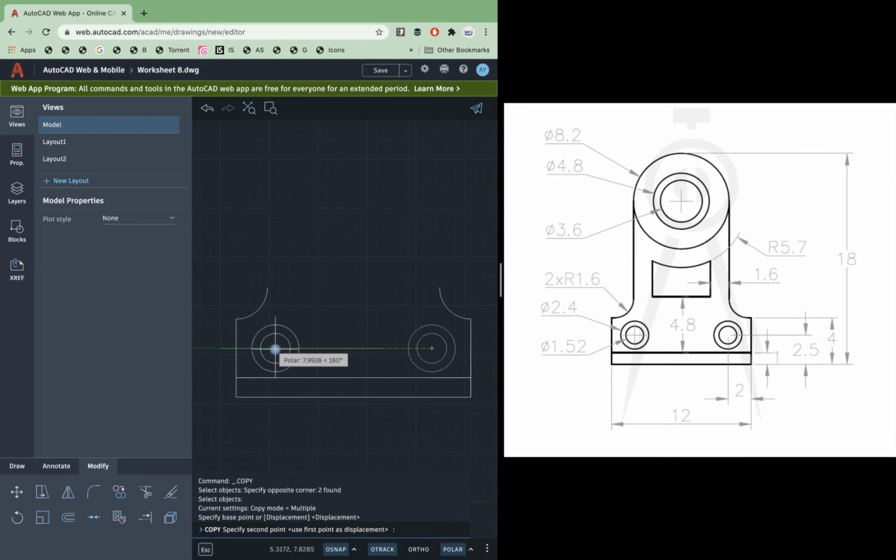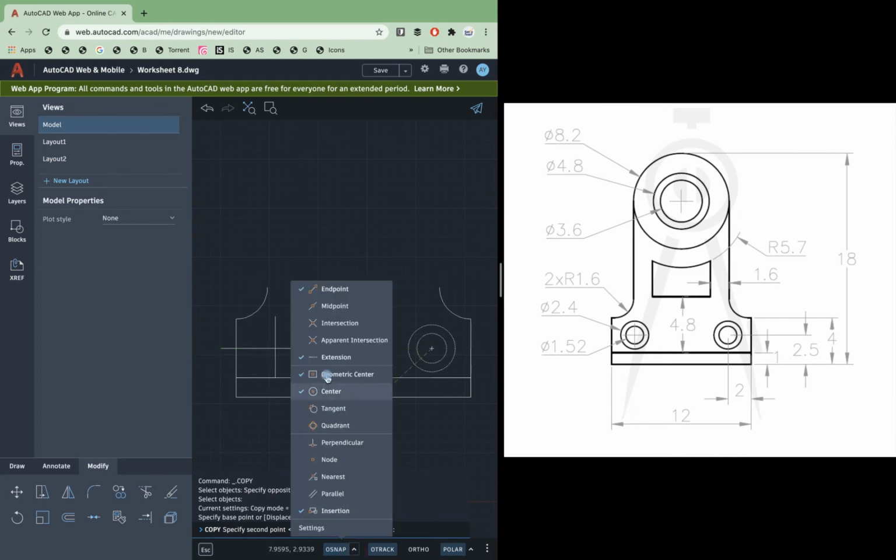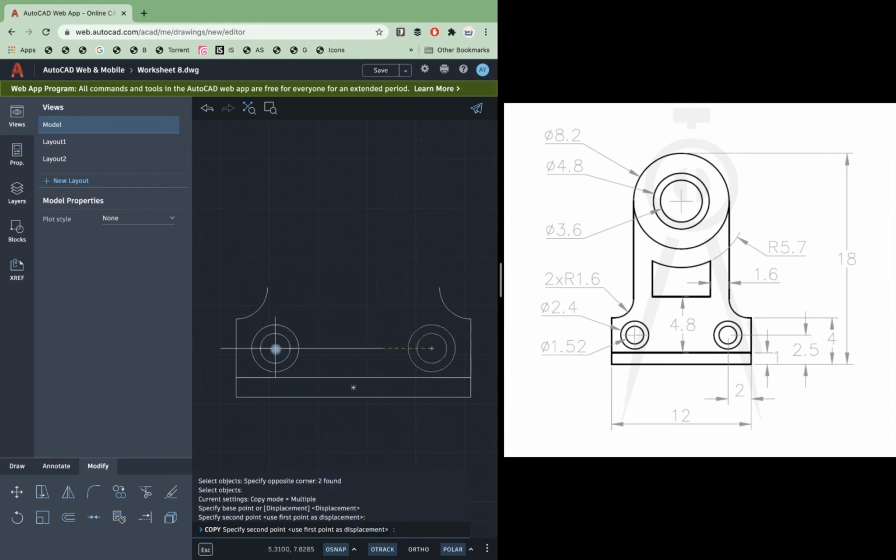Okay, now actually, let me turn on intersection. Yeah, after turning on intersection, it will definitely snap to the intersection. Click here, now hit enter to come out of the tool. Now just like the previous one, use the trim tool to clear these lines. Sorry, it's taking a bit longer, but this is how we have to do it.